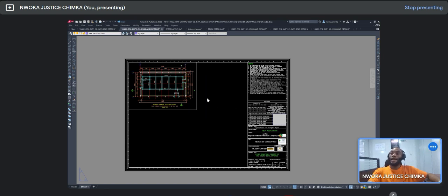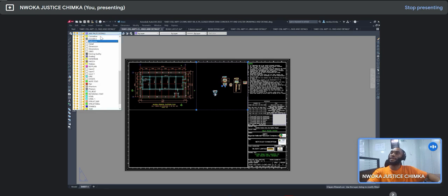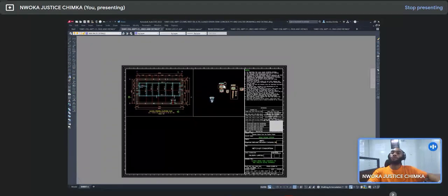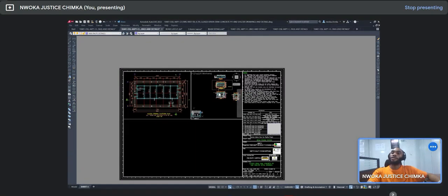Okay, so I still have more space here to create other drawings, which I can still do. And so I'll have to do again MV, enter, and now let me create for this other one here. I'll create from this space here to bring out another section because I still have more drawings on that place to work with. And then I'll still convert this now to a layer, depth point layer, and I'll choose depth points. Okay, now once I've done that, I'll now double click on this place. I want to bring in this my section, which is here on this place here.